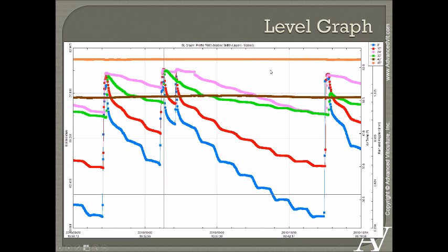So you'll notice that there's nothing happening at these two levels. Well, the fact is there's no roots there. When you see the activity uptake at these various levels and you don't see it at some levels, that usually means there's no roots. And in fact, we did a backhoe pit in this location and found about 36 inches of actual loamy soil overlying a very discrete boundary change to a bunch of gravel. Roots don't want to grow in the gravel. Actually, water doesn't want to go into the gravel. Water from irrigation doesn't like to go in the gravel if it's drip irrigated. Rainfall will, but drip irrigation doesn't like to, and rarely does.